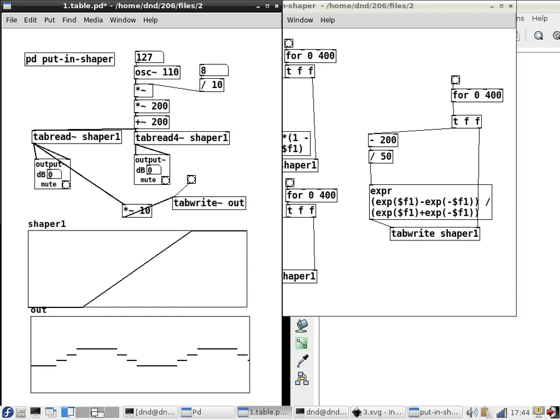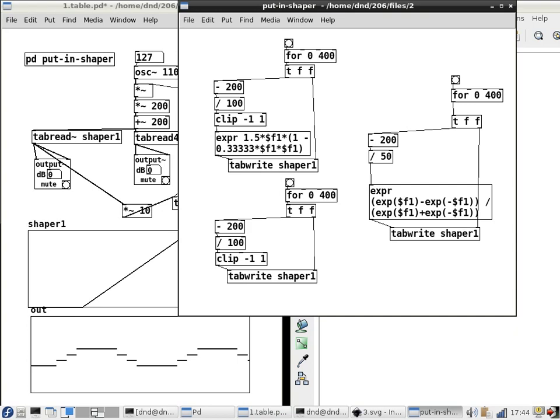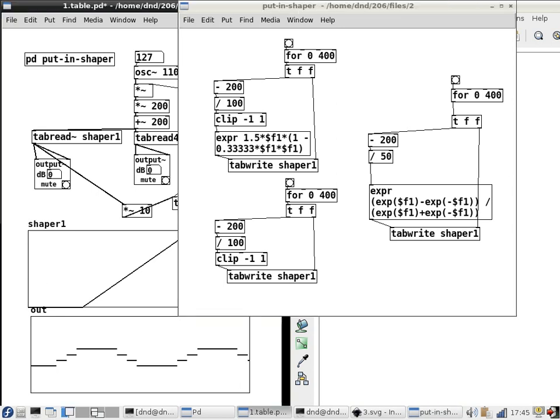Well, I had to draw for you last time because I didn't have the wherewithal to throw things into the table so that you could see them. Now, this is a good example of when you don't put something in a wavetable, for two reasons. One is this is really just the clip function, so why don't you just say clip instead of having all this garbage to look the thing up in the table. And indeed, last time when I was squaring and cubing signals, it was much, much smarter just to throw multiplies down than it was to throw the thing in the wavetable.